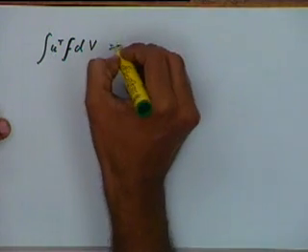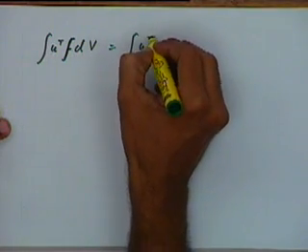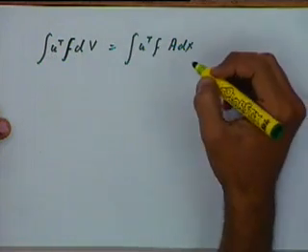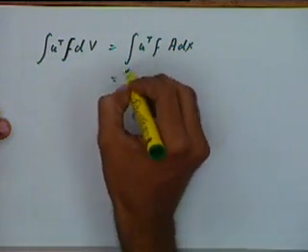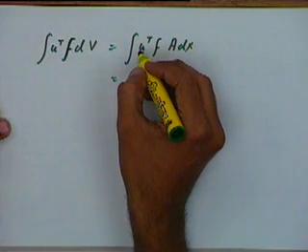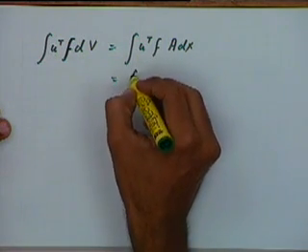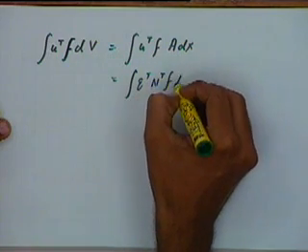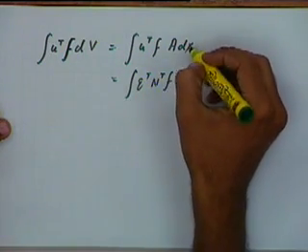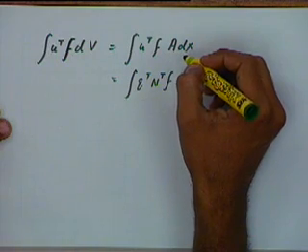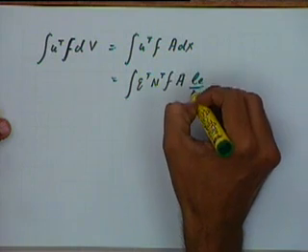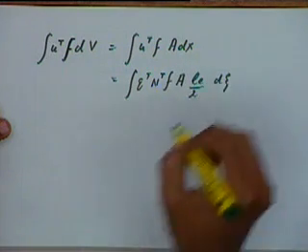This is nothing but integral of U transpose F A dx. This will again be U transpose as n times Q. So, this will be integral of Q transpose n transpose F A dx. Again I will convert that into terms of d zeta, so I will get this to be LE by 2 times d zeta.